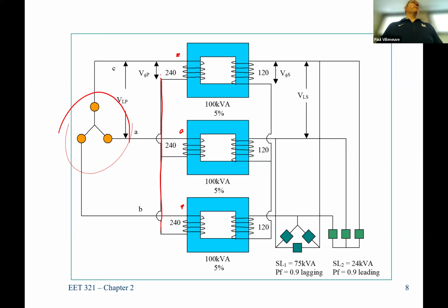So it makes sense, if you can, to buy single phase transformers, because it's pretty easy to wire them up. That's why in the utility, if you drive up and down Stillwater Avenue, when you see three cans on a pole, that usually means it's able to provide three-phase power.